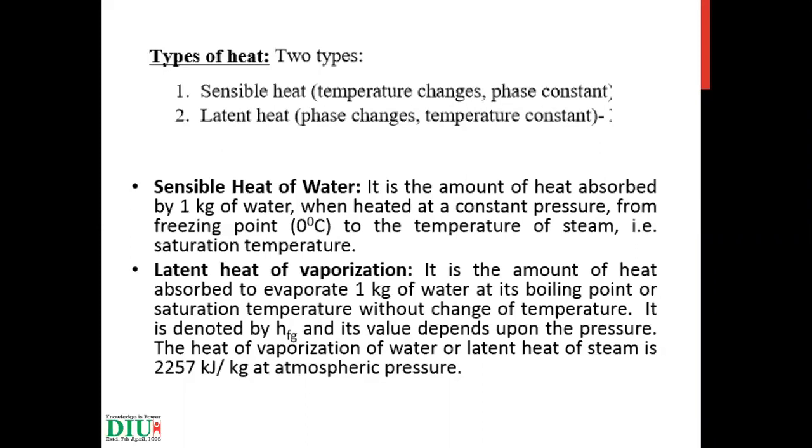Why? Because you have taken 5 kg of water. Suppose after some time 1 kg of water has converted into steam, but still 4 kg of water is not converted into steam. Those 4 kg are still in water form, not steam form. So that steam is known as wet steam because that steam may have water particles or water elements. So that is wet steam.